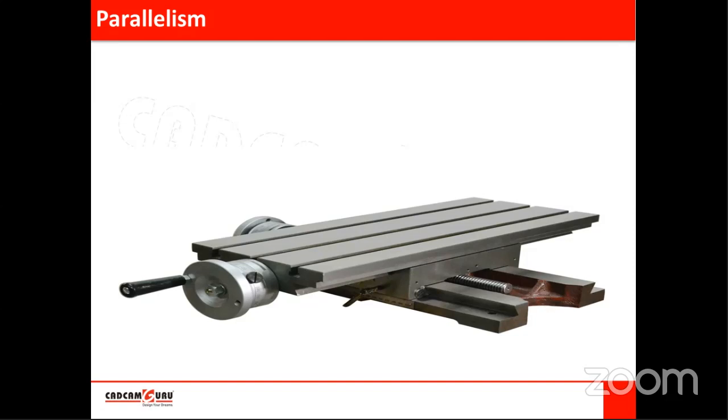If there is an error in parallelism, one surface is not parallel to the other, then we cannot move that drawer properly or smoothly. Okay, so the drawer motion will not be smooth. I think you might have experienced it in rainy seasons. In rainy seasons, that plywood or wooden material gets some bumps on it due to moisture content in the atmosphere, so it loses its parallelism. Meaning the surface does not remain parallel. So we feel that difficulty while pushing and pulling that drawer, right? So for smooth motion, these guideways or slideways should be parallel to each other.